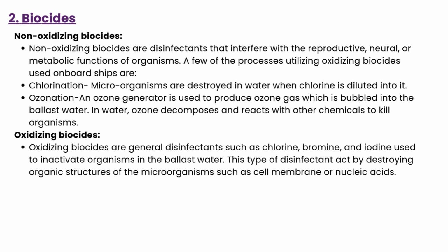Non-oxidizing biocides are disinfectants that interfere with reproduction, which we have already discussed. And what is the difference with oxidizing? The oxidizing biocides are generally disinfectants such as chlorine, bromine and iodine, which we had discussed earlier.